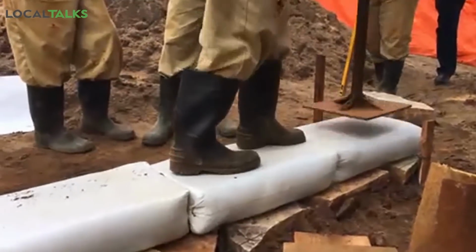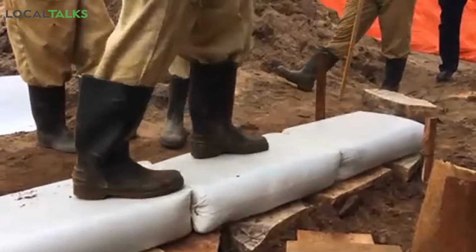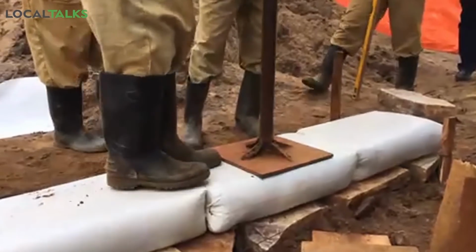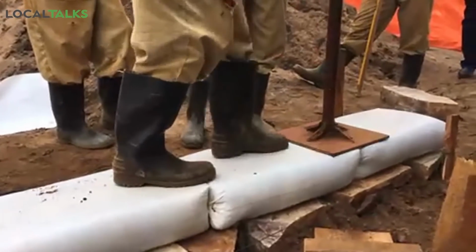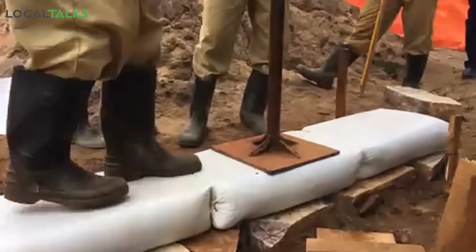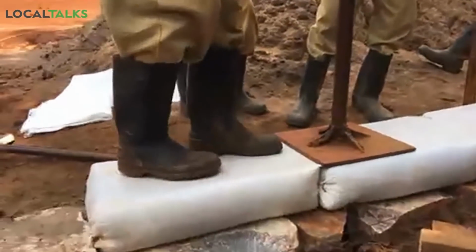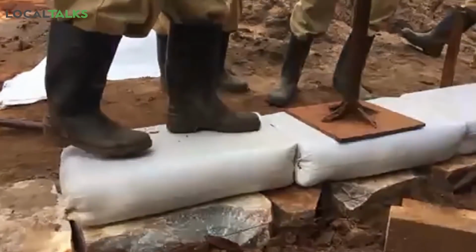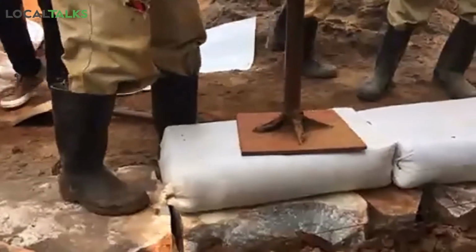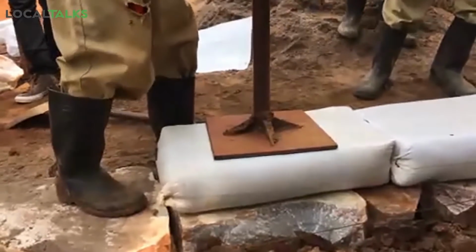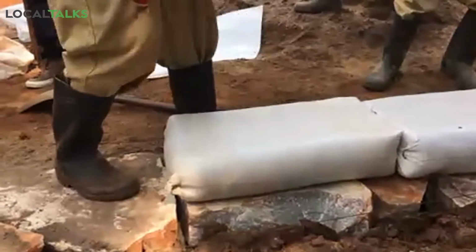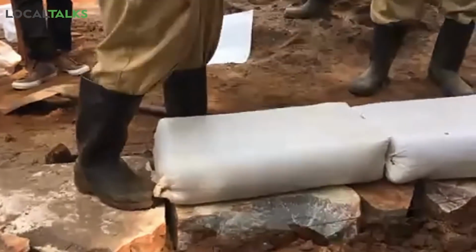I think I asked just when to stop. The sound changes. That is interesting information, that the sound changes once our target compaction has been reached. Is it the sound now, or not yet? Yeah, that is the one we are looking for. Not that. There you go. And that is a sign that we have reached the level of compaction that we're looking for.